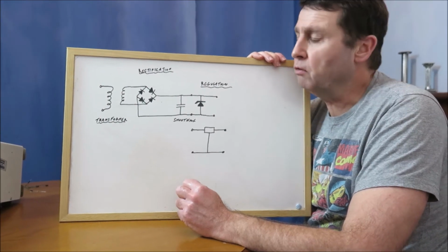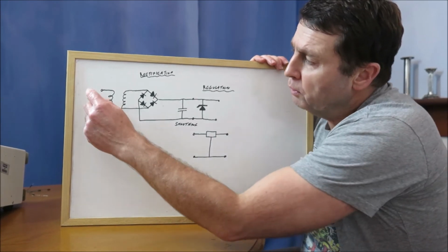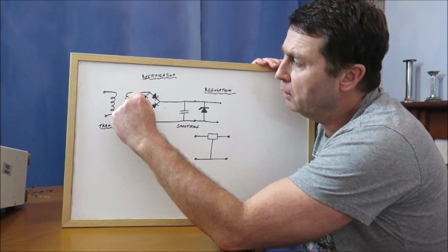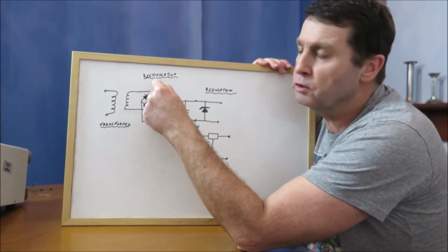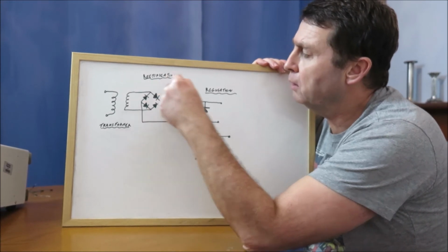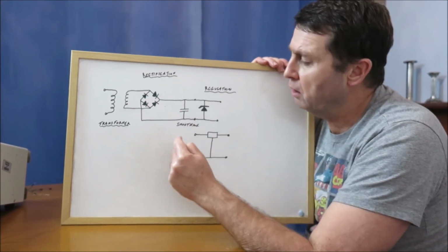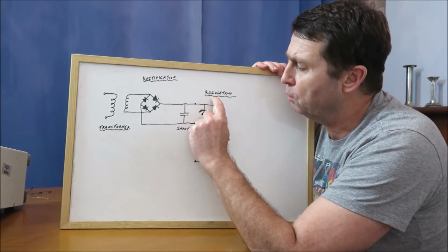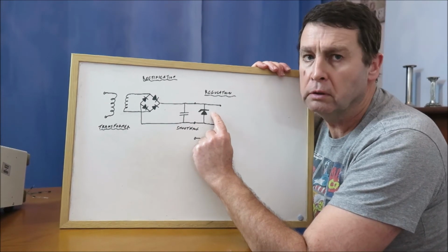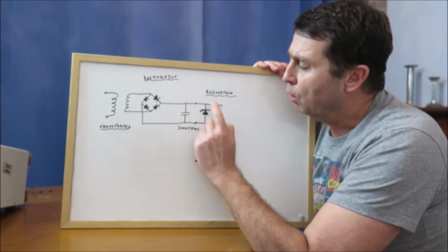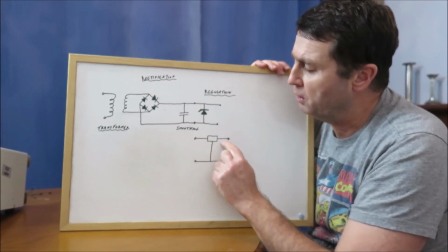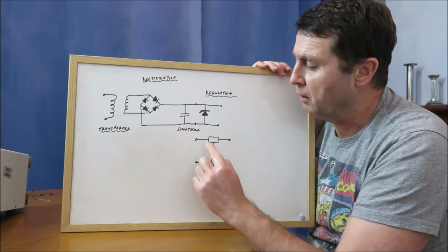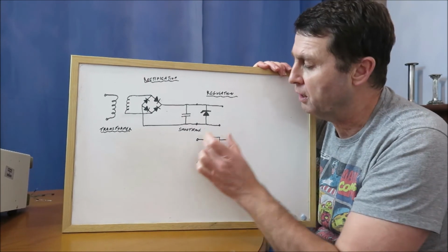To look at a circuit diagram then of our power supply, we've got a transformer coming in, taking our high voltage to a low voltage. We've got the bridge rectifier, so it's doing the rectification stage. We have a capacitor across there, which is doing the smoothing stage. And then the regulation for the fixed voltage output, the regulation here being done by a Zener diode. Or if we take that section out, we can put our 3-pin device in there, which you can see the 3-pin connections of our encapsulated voltage regulator there.